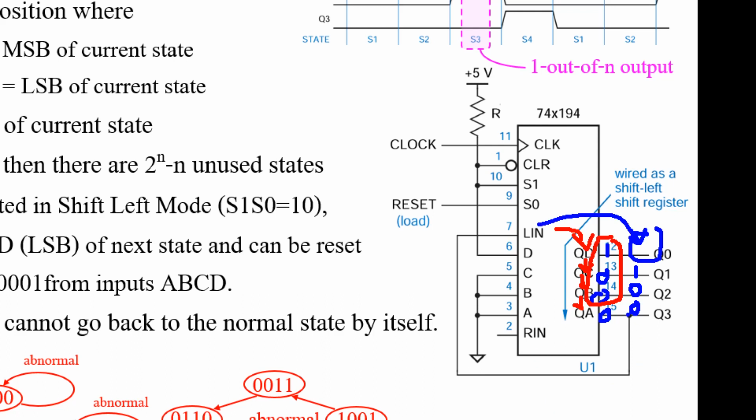And now I need 0, right? 0 at here. So that it becomes 0 at here. After that, when the next clock ticks, these 3 bits are copied and shifted down. And this bit now is L in. That means the 0 will update here. And for the next clock tick, these 3 bits are copied and shifted 1 position down.